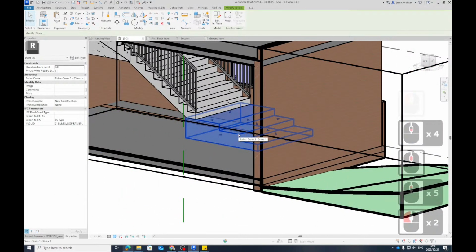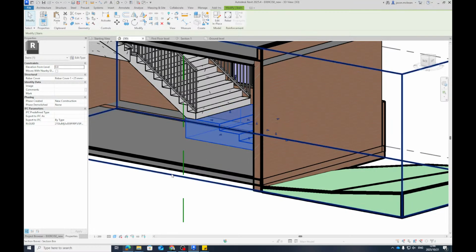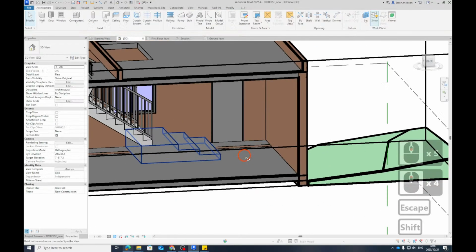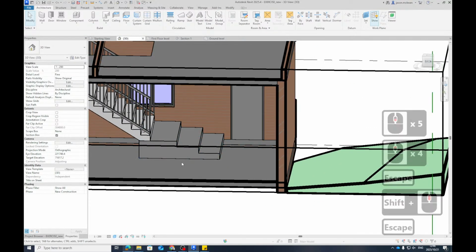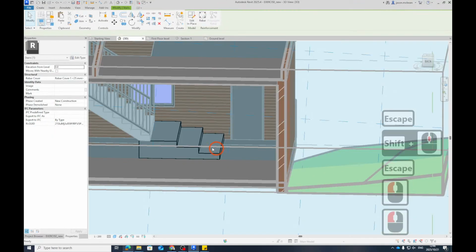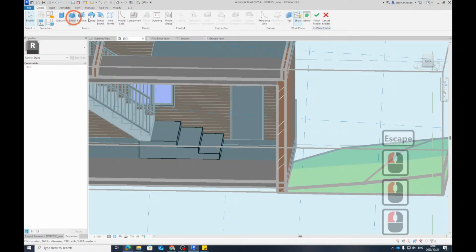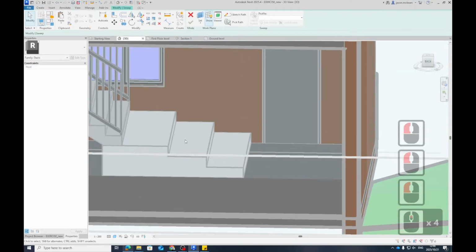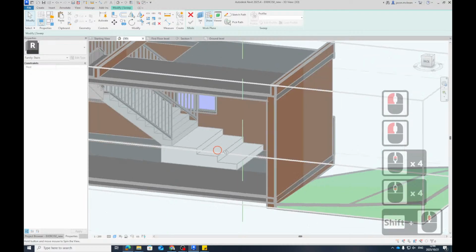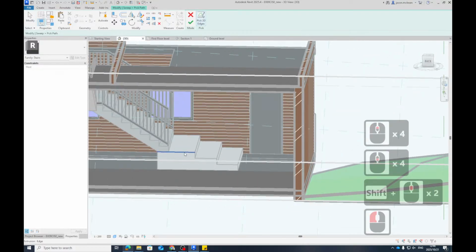But you can maybe make this extrude out. You can make them go in all directions so it comes up. That's a different type of extrusion. You're going to use a sweep to do that. So I'll keep this here. This is crazy now. So I'll keep this in place. I'm going to go edit in place. So maybe I want to do the same thing, but I'm going to use a sweep instead. But you're still going to need the extrusion here in the middle, and I'll explain why. I'm going to pick this edge and that edge.